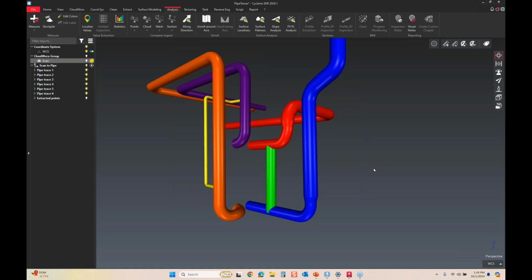I don't recommend it because now you're working with a scale number. And if you get that off a little bit at all, now we're not sure if those measurements are accurate. So I would tell you, no, do not scale.